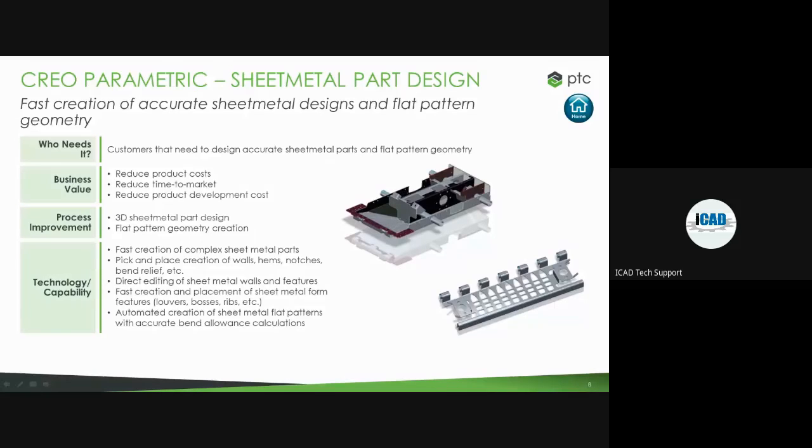For the single sheet costing, or if you want to order the raw material sheet, we need the total requirement of our product development length. By using sheet metal part design, some very easy tools are available. By using these, we can easily get the flat pattern geometries, and we can give this development length for design and manufacturing very easily.